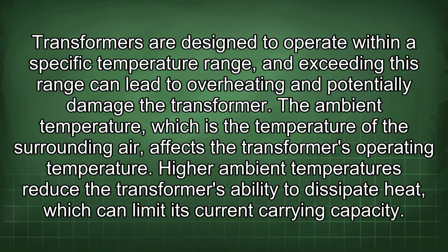Transformers are designed to operate within a specific temperature range, and exceeding this range can lead to overheating and potentially damage the transformer. The ambient temperature, which is the temperature of the surrounding air, affects the transformer's operating temperature. Higher ambient temperatures reduce the transformer's ability to dissipate heat, which can limit its current carrying capacity.